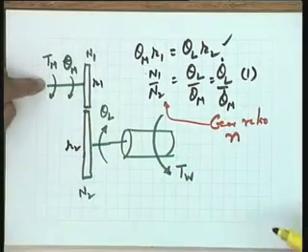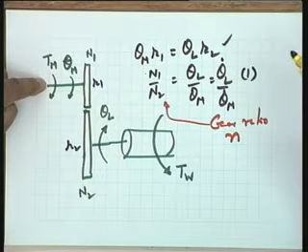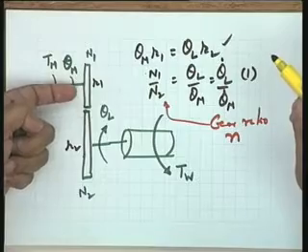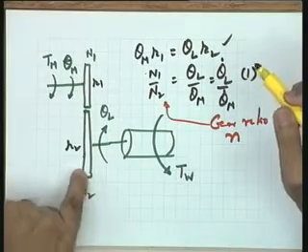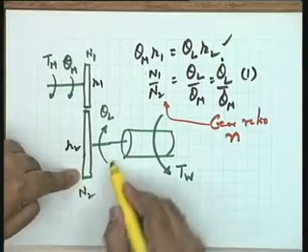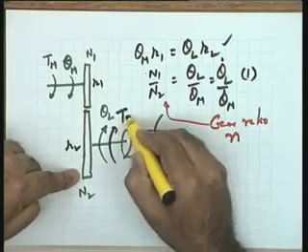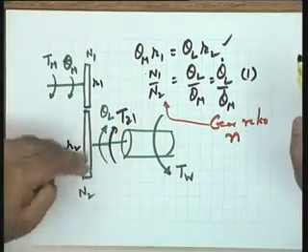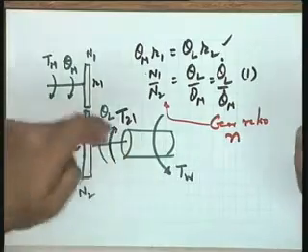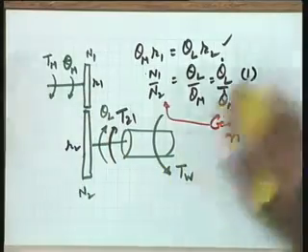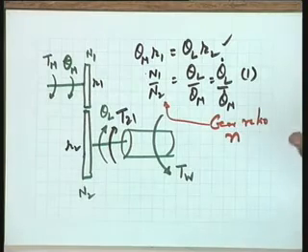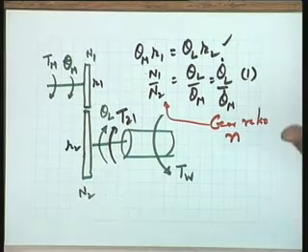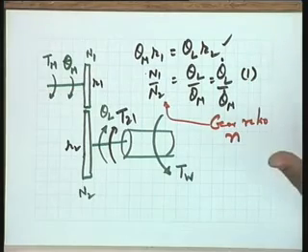Okay. Now look at the torque expression. Now you see Tm is the torque generated by the motor. Now let me assume that the torque transmitted to this particular shaft is T21. T21 is the torque transmitted through the gear train onto the load shaft. So T21 is responsible for driving the inertia against the disturbance Tw. You see this point, T21 is responsible for driving the inertia against the disturbance Tw.